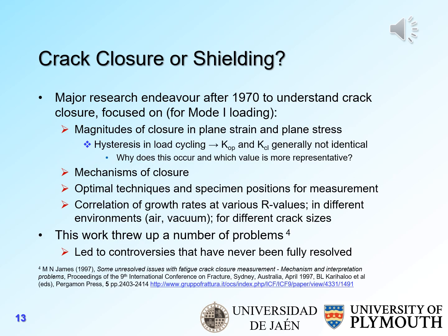Crack closure has proven to be particularly interesting to the fatigue community, and a major research effort after 1970 has been focused on understanding it. And this is focused on things like the magnitudes of closure in plane stress and plane strain. Does closure in plane strain exist? The hysteresis in load cycling between K opening and K closing, which are generally not identical.